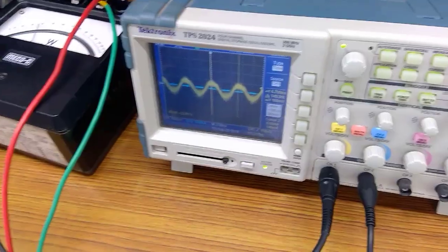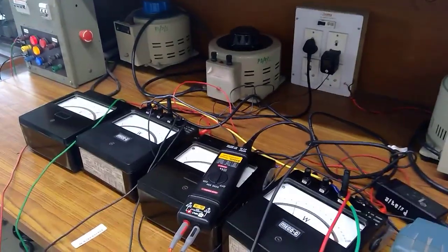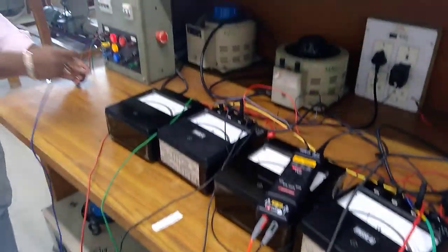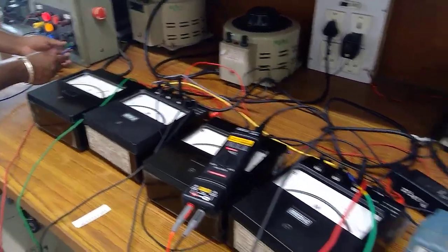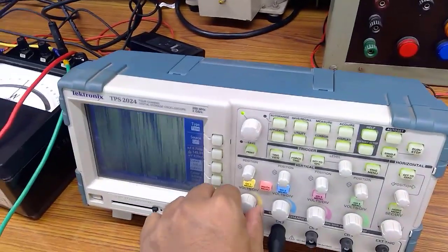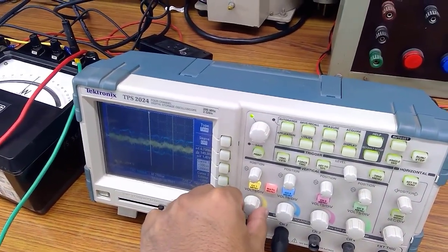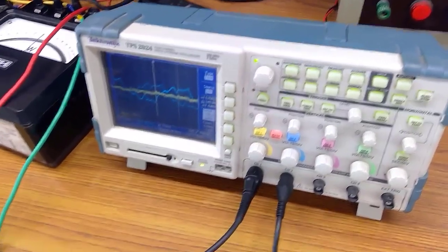Now what we will do is we will short the neutral of this star point through a wire to the ground there. Okay. So though we are doing it online, it's better to remove it, right? So you see the voltage waveform, there is no harmonic component in it, right? It is almost 0 here.